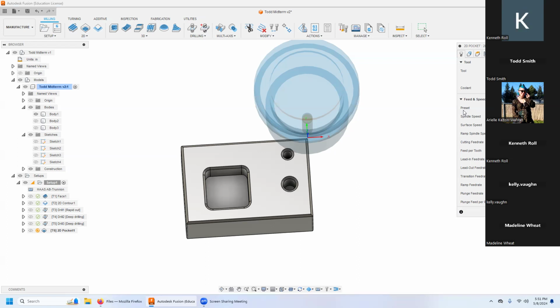So the question was, if the machine cannot run that fast, will it error out? Some brands, yes, some brands, no. And that's the problem. It will still keep the same feed rate. So now, if we have it set for 12,000, but it can only spin up to 7,000, it will still try to feed at 106 instead of, as we see here, 60.